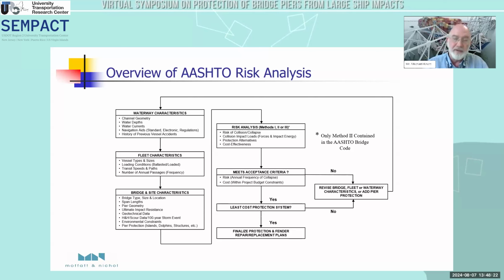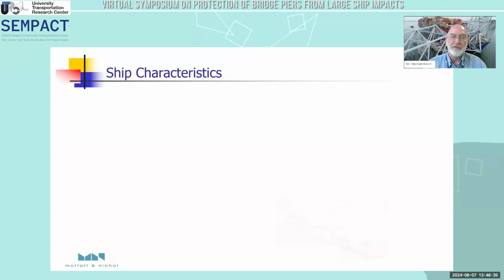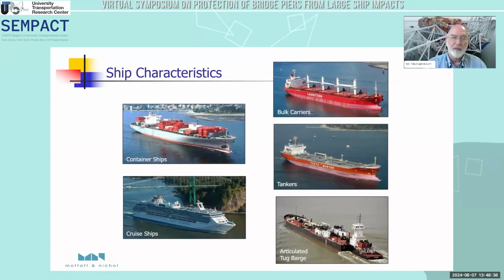Well, if it doesn't meet the criteria, then something has to change. Either add pier protection to protect the bridge. If it's a new bridge, make the spans longer. You continue through the analysis until you arrive at a solution that's acceptable.